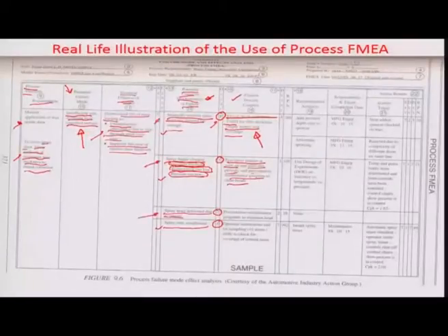So the best idea is to check at every shift end or beginning whether the dispenser is properly dispensing, by spraying a pattern and seeing how much of it is covered. So that is one preventive maintenance step for the current process control.